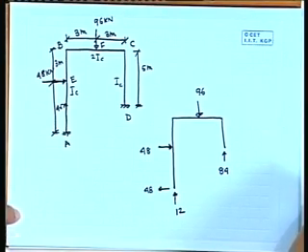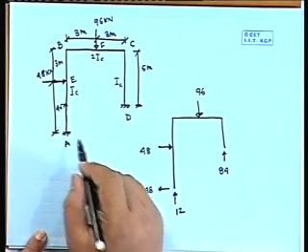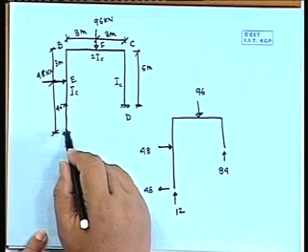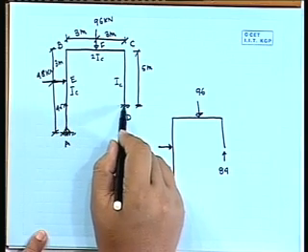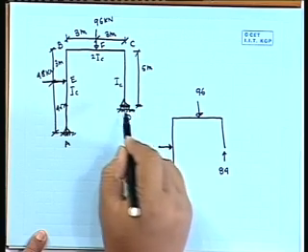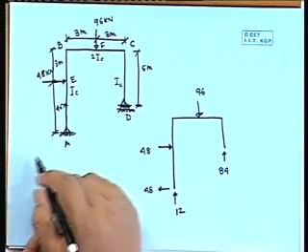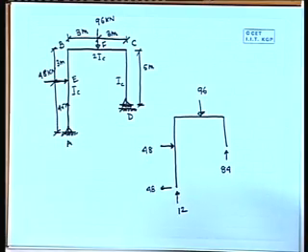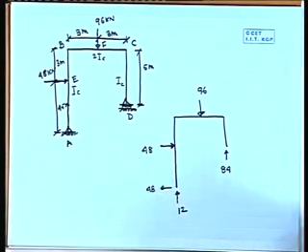The support condition is different. The way I have put it, it will not be clamped, so it will be a hinge type of support, right? And this side should be a roller type. If it were fixed at both ends, we couldn't solve it because it would be a statically indeterminate problem. That part we already did, up to the reaction part.